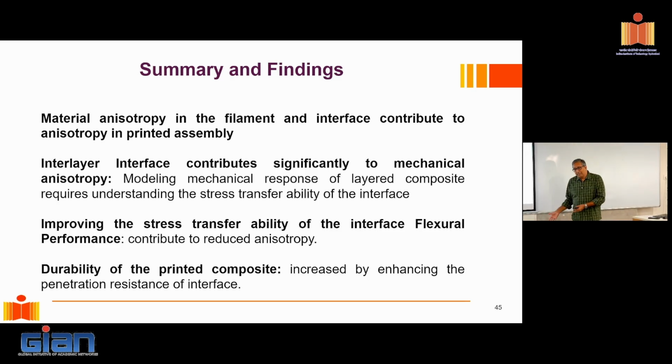Now, whether we can port the same mechanics from cast concrete, I think that is going to be unconservative at some point, because it does not address this issue of shear transfer across the interfaces, right? So, whether we can treat the printed filaments as concrete, having a compressive strength close to the compressive strength in the weakest direction, and port all our design equations around that, I think no, that would be a mistake.